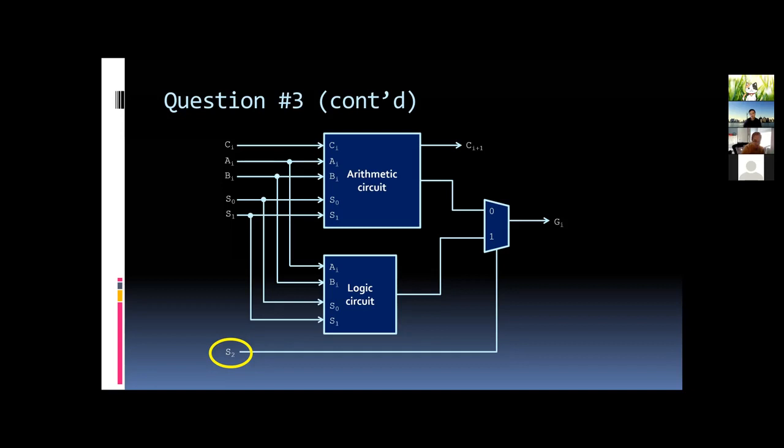Essentially, that's an input into the mux, right, that decides which results to go. So if it tells us to take the first parameter, that would act as an arithmetic unit. If it says the second, it's going to take results from the logic unit. Okay, so this is essentially the control unit that selects arithmetic versus logical, right? And this is how it works from high level. You see, from high level, the operations of the ALU, at least the basic questions, are not that difficult. So I want you to understand how it works.